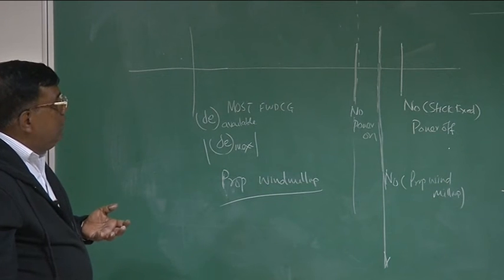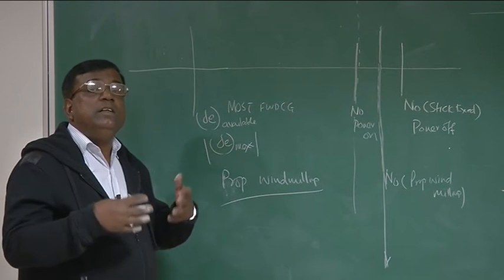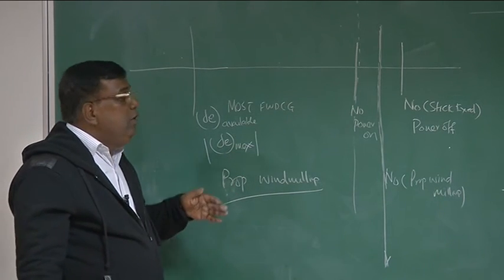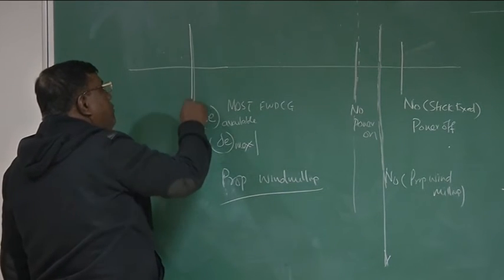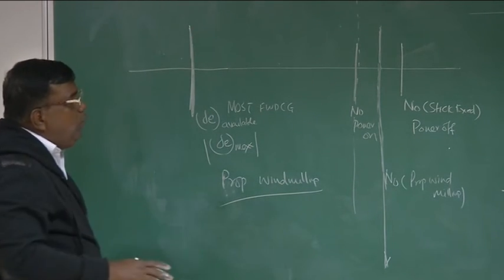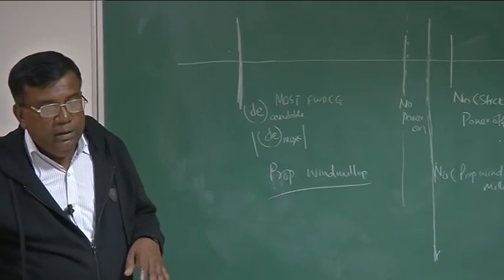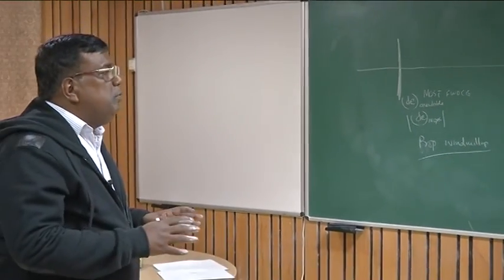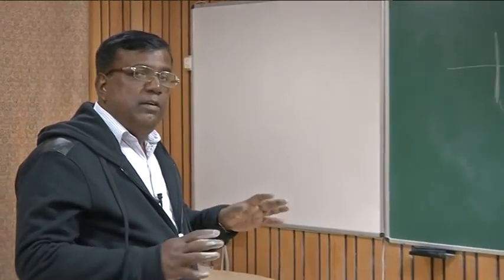Because what will happen, as I move the CG forward and forward, delta E max requirement will go on increasing, we have seen that. And since there is a limit on delta E max, say plus minus 25 degrees, forward CG will be more governed by this. So this is the limit I am putting here. And if you know these three, four things, you will be able to handle this sort of situation. As we progress, when we go for a little bit on stick free, we'll again come back to this neutral point and address these things from the designer's perspective. We'll solve a problem and we'll try to get a feel for this.